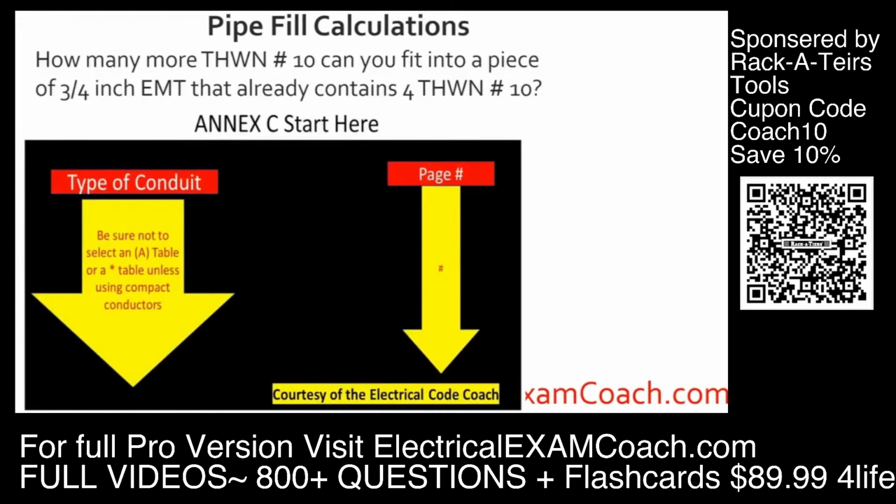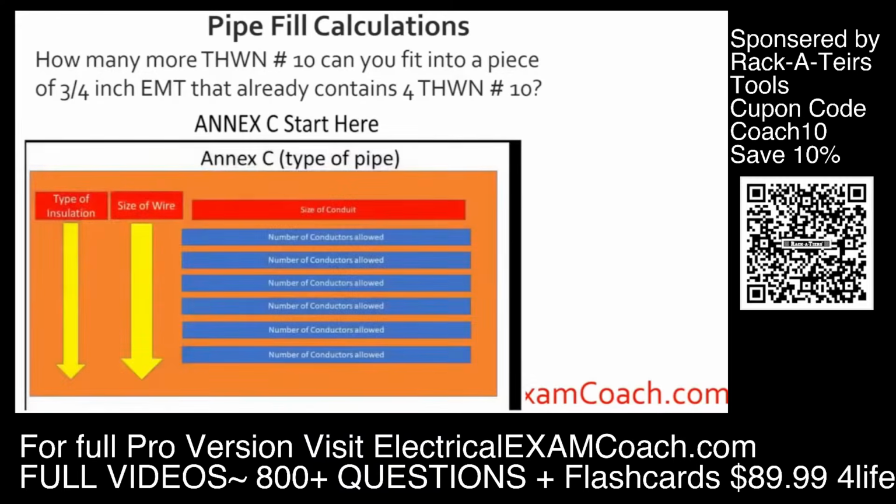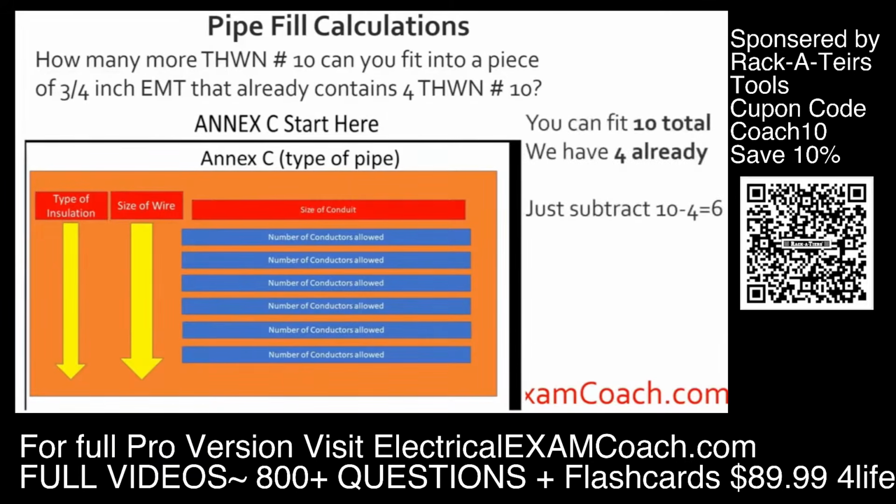Then we cross over and find our page number. When we get to the actual table, we're going to read the black bold heading to make sure we're in the right table. Then we're going to find our type of insulation under the insulation column, find our wire size, and then come across the top to our size of conduit and tee off with our answer. And we find out that we can fit 10 originally, but our question states that we already have 4 of them in the pipe. So all we have to do is do a little third grade math. We take 10 minus 4 equals 6, and we find out that we can fit 6 more inside of this conduit. Great job.